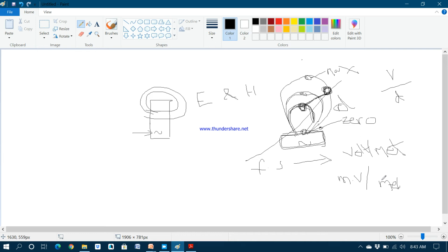This is the field strength pattern and the radiation pattern. The radiation pattern of an antenna is one of the important characteristics of an antenna, because by observing the field strength characteristics, it indicates the distribution of energy radiated by the antenna in free space. Whenever we calculate the strength of the wave here, automatically we can calculate the power radiated also.